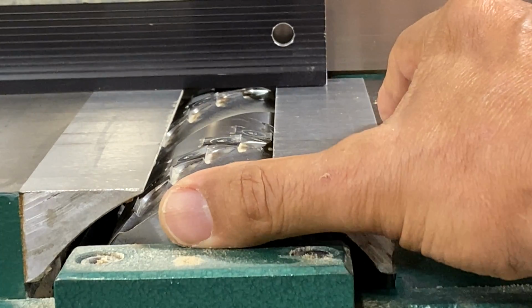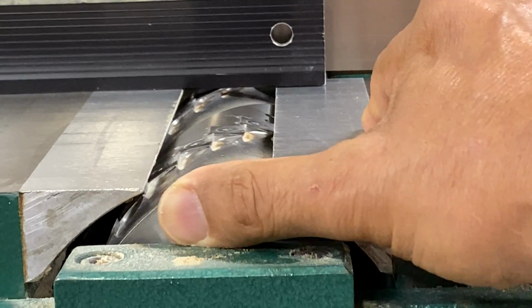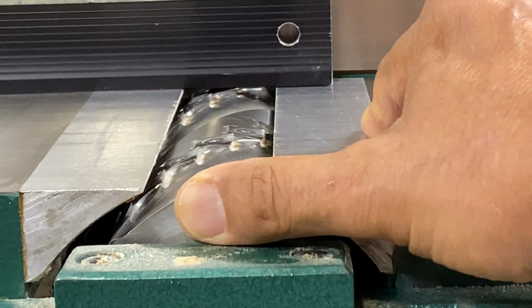While this is not a comprehensive guide, these are the main things that I check on a regular basis. First of all, I take a straight edge and place it over one of my cutters. If you have a 3-bladed jointer, put the straight edge over one of your knives. Then with the jointer unplugged, rotate the cutter head and the cutter should just kiss the straight edge like this.